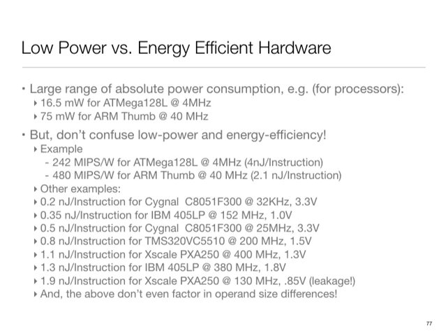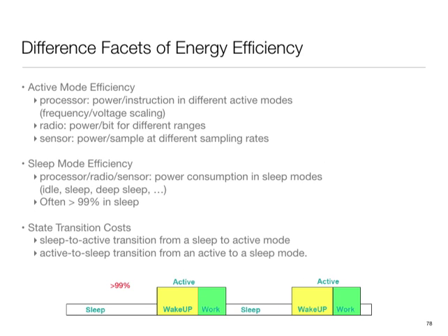Simple things have lower static power just because they are simpler. They can more rapidly wake up and change state. But if you throw a big task at them, they will take more energy. For example, take an ARM A15 versus an ARM A0. The A0 would be very good if my task was to measure the heart rate every second. On the other hand, the A15 would be better off if I'm looking at the energy consumed to do an FFT over a collection of subsamples. So they may shine in different settings. Again, don't go by the power number alone because it hides a lot of nuances behind it.